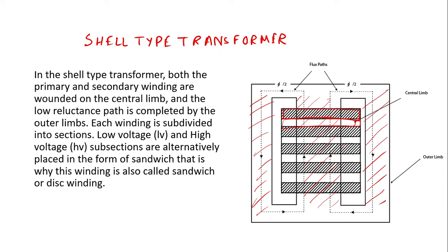So the lamination here is also reduced by producing a free pathway for the flux to flow, right? If the flux flows through a pathway over which the coils are wound, the coils would conduct some amount of current according to Faraday's law, right? So to reduce that current, we need lamination. So lamination material is also saved by this methodology.